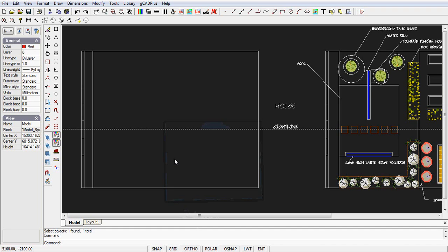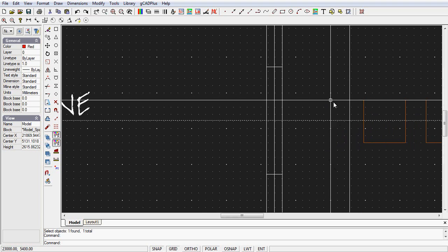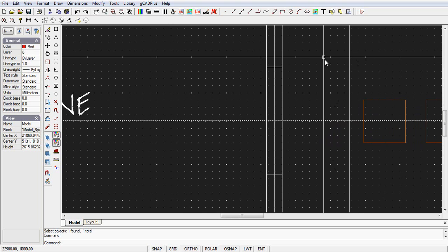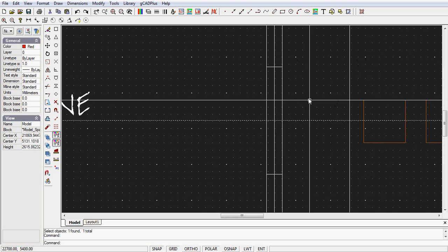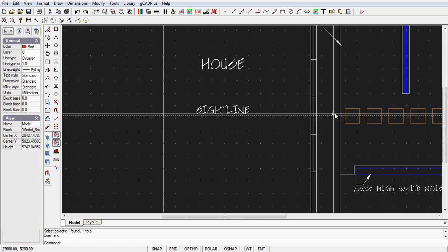We can't avoid being precise and careful about putting measurements for the location of boundaries and position of walls and windows, as we've been doing. But now it's time to show you the benefit of the fact that we've got a grid on. If we zoom in on any part of the design, you'll see the grid starting to appear, and if you go right in, we've got a 100mm grid here with 5 steps per half metre, and you can see the detail as we go in.